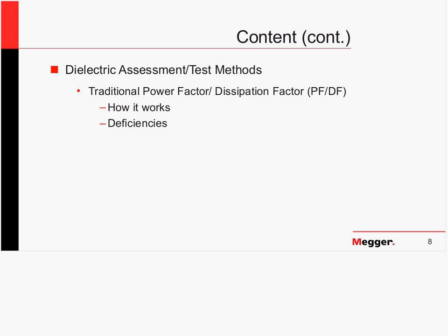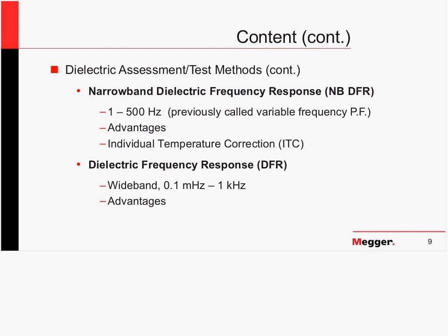I'm focusing on 3 key dielectric assessment methods today. First step will be a traditional power factor test. We will review how a power factor test works, and I'll be candid about the expectations you should build around its use. Deficiencies are what promotes change, so this is an important part of the conversation today. This will lead us to the final part of the presentation, which introduces DFR testing, or dielectric frequency response testing.